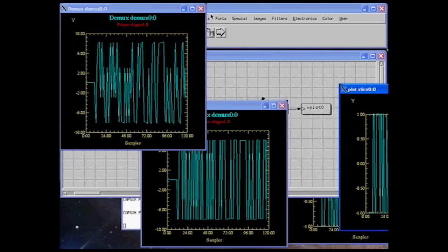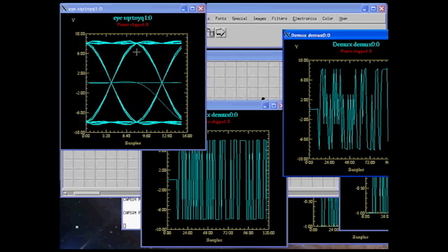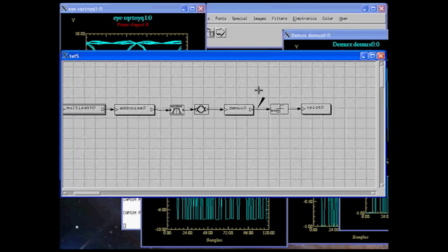So even though the eye diagram obviously doesn't change, we're sampling around here, and you'll notice that we're not at the peak anymore, and occasionally we get different levels, which indicates that we're not sampling at the right phase. In a typical digital communication link, you would have to do timing recovery and actually estimate the correct phase for sampling where the match filter peaks. Of course, we're manually setting that in this digital communication link. We have other simulations that actually do that and estimate both the timing, do timing recovery, and correctly sample at the right phase automatically. But that's a topic for future discussion.